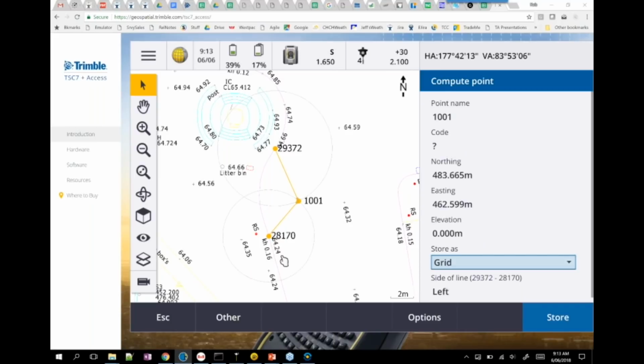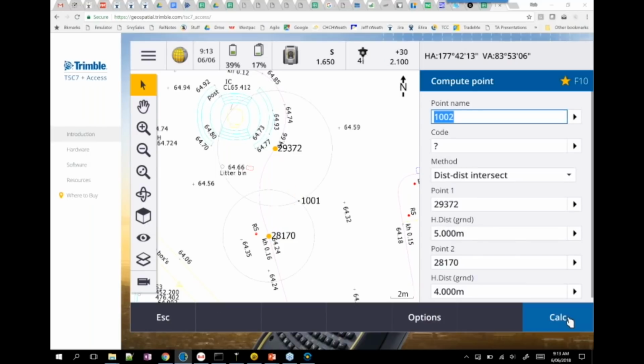So we're getting some construction work to help us decide which point we want to create. Once we make the decision which one we want, we can hit store, and it's now stored that point. That's showing the power of having the map up at the same time and seeing the form on the right-hand side and getting some nice interaction between those two. In the past with Trimble Access 2017, this would have been an awful lot more complicated and not nearly as straightforward. So we've made this nice and simple.